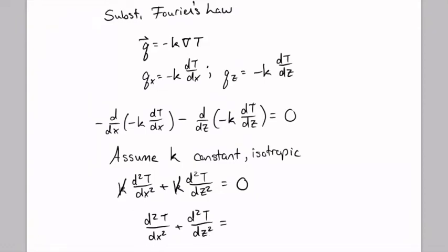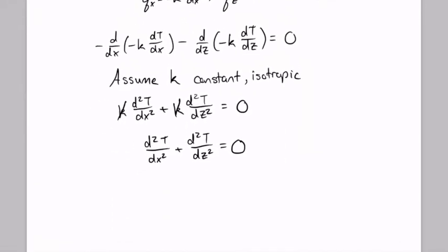And that may seem a little bit surprising, but if you think about it, it's basically just saying that it doesn't matter whether that slab is copper or plastic or cement. If you wait long enough, the temperature profile described by this equation will eventually result. And that's a subtlety of the Laplacian form of the heat equation, which is basically when you have no generation nor accumulation. If we were to have a generation term in here, things would get a little more complicated because you would have a k dependence.